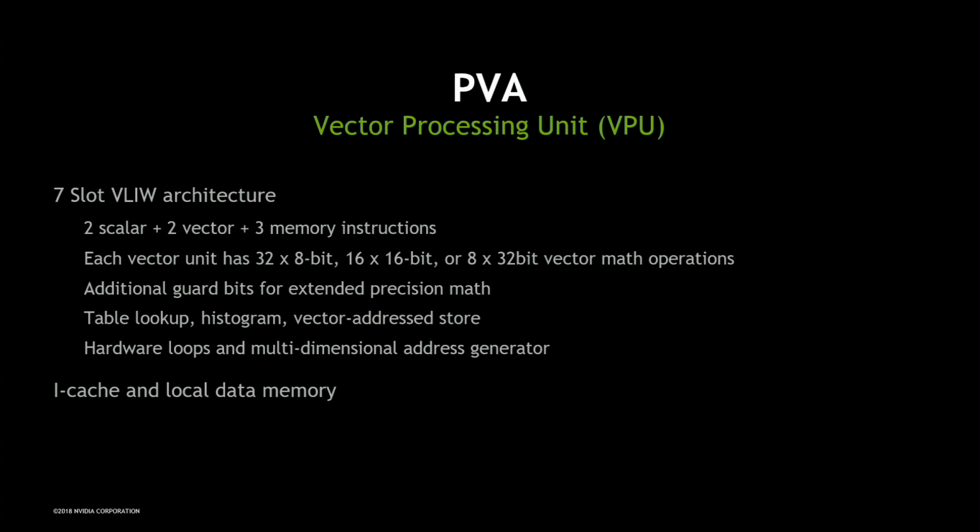And then we have this DMA I mentioned. So PVA and the VPU is basically working on tiles of memory. And we have a DMA that handles most of the address calculations, the address offload, and keeps the unit fed as a side unit processing along the way. To feed the VLIW, there's an iCache, and as I mentioned, there's a vector memory there for local data.